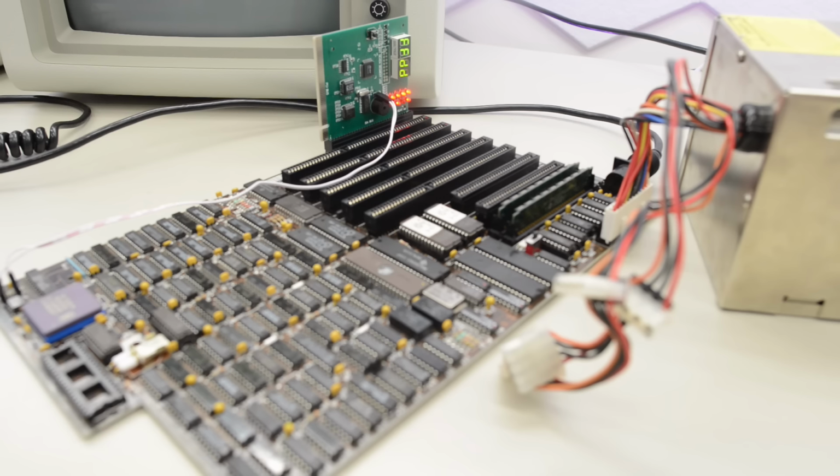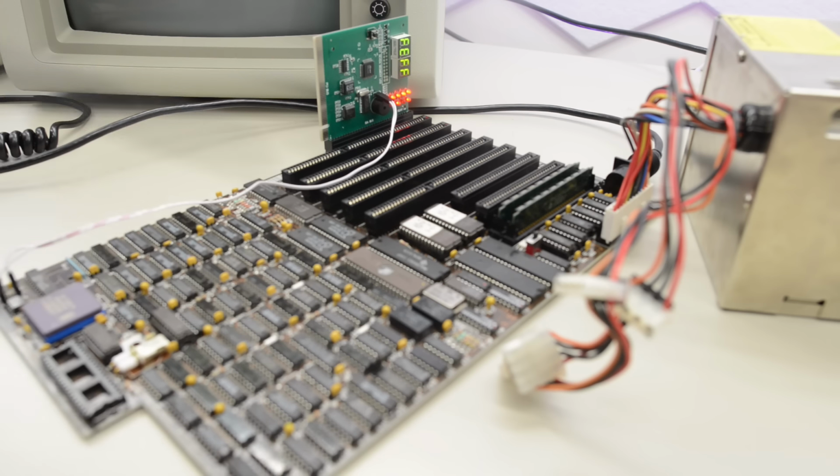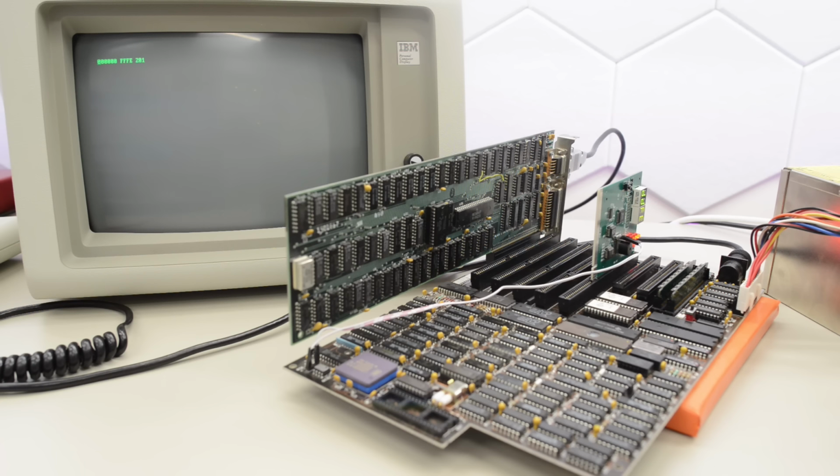In the 5162, conventional memory addresses 0 to 512 KB reside in the two SIMs. I have replaced the fake bubble RAM with known good SIMs from another system, but that didn't help. I have also disabled these onboard RAM chips with jumper J10, just to eliminate one potential problem. To make sure my CGA card hadn't gone bad since I used it last time, I replaced it with an MDA card. Then this happened.